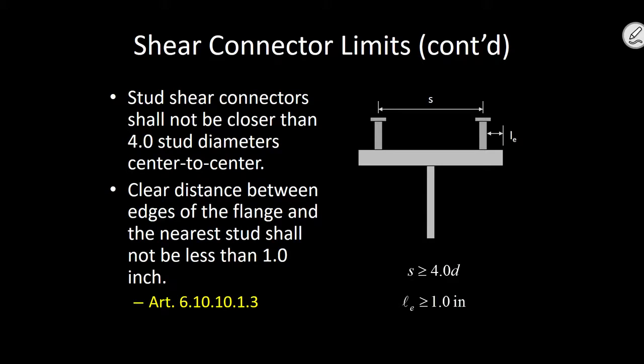So if S is the transverse stud spacing, it must be greater than or equal to 4 times the diameter. Okay? So that's one stud spacing requirement you must meet. The second one is that this clear edge distance has to be greater than or equal to an inch.